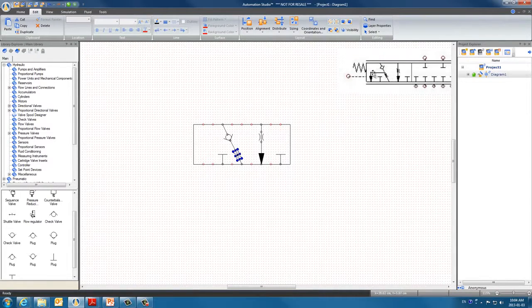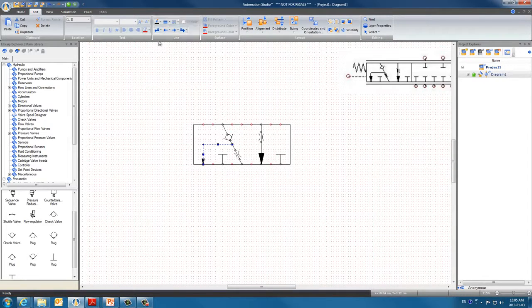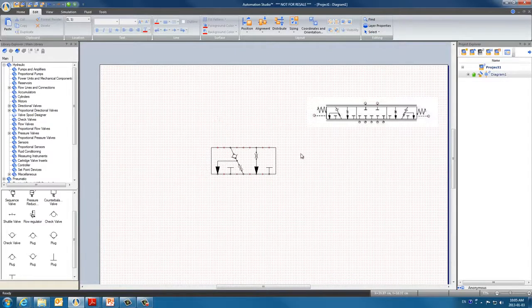Next, to create this line, click on the port and find the right position and double-click. Now we need an arrow here. Select the line and the left arrow since this is the beginning of the line. Again, we choose number 9 at 100%. We have completed configuring this left spool, so now we can generate the spool and save it.